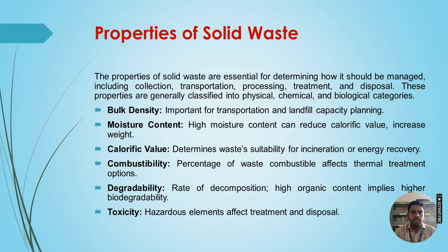And coming to calorific value, we already know that calorific value depends upon the temperature. It determines the waste suitability for incineration. Incineration means we have to apply the temperature under aerobic conditions. So what type of temperature we apply on that waste depends upon the calorific value.